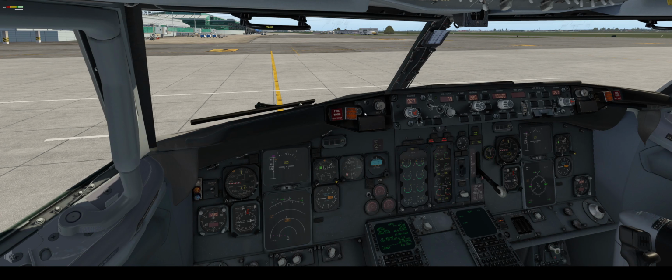There are some limitations with altimeters I will not discuss. Crosswind component is a little bit higher. It's 35 knots. Why? Because we don't have the winglets. If we have winglets, the limitations will be slightly different. Regarding the weights, it depends on variant. You have 300, 400, seating capacity, and so on. So basically that's it.